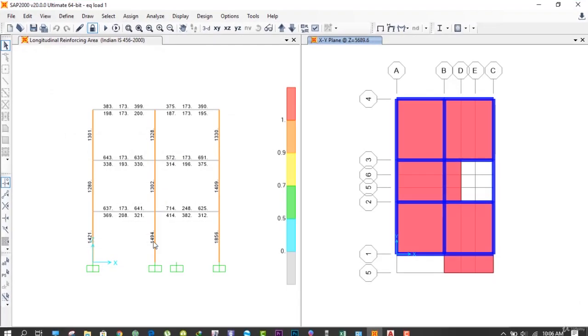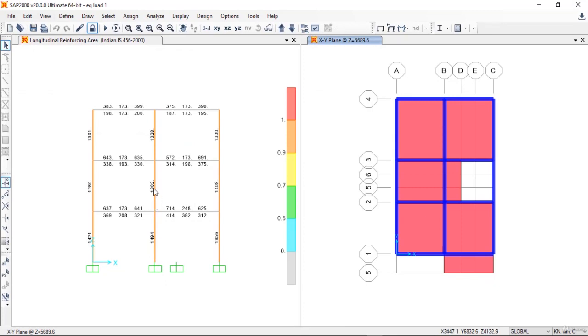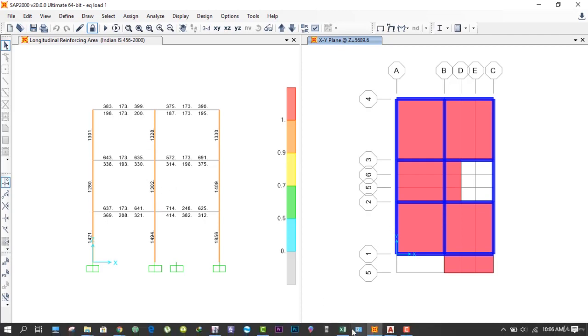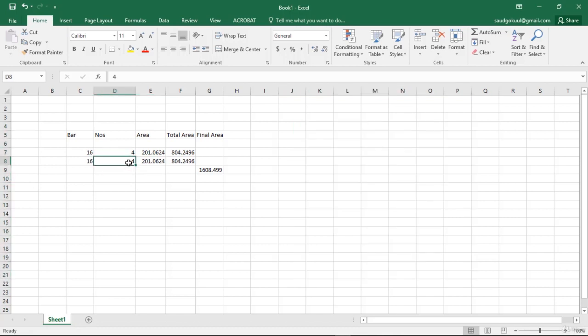After that we got 1302 at the mid floor and 1328 at the upper floor. Earlier I told you that we go from higher to lower values, so we take 1328 for this floor as well. For gaining 1328, we convert the 16 to 12. It gives us 1256, and let's see if 6 numbers of bars help.